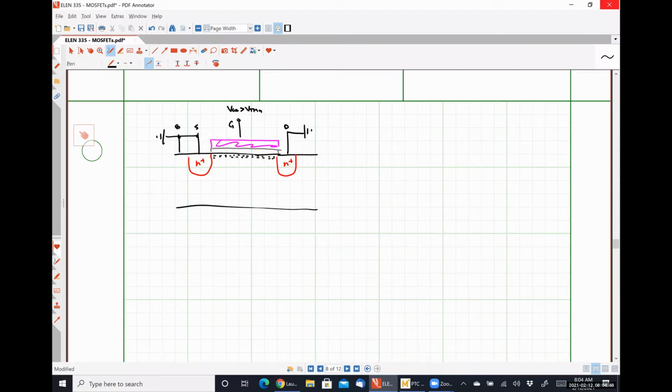You've got it. So these are field effect transistors, okay? The gate voltage establishes kind of a collection of free charge. But you need a potential difference between the source and the drain to cause current to flow in one way or the other. So if VD is now greater than 0, we have an electric field